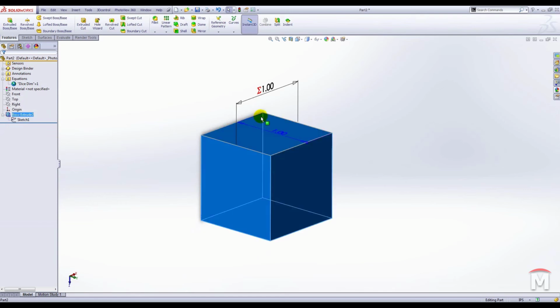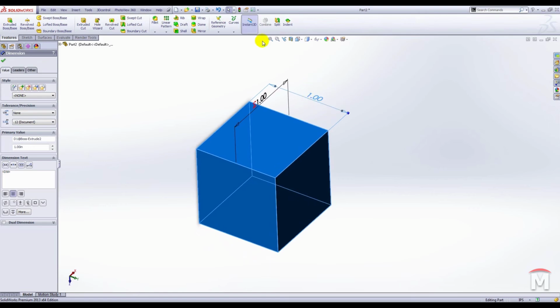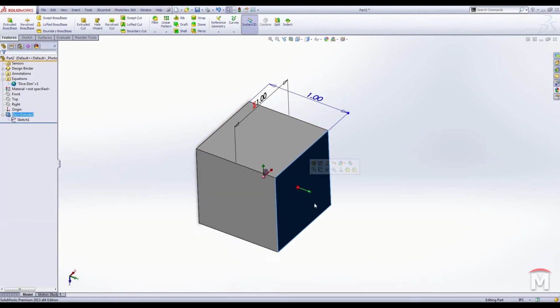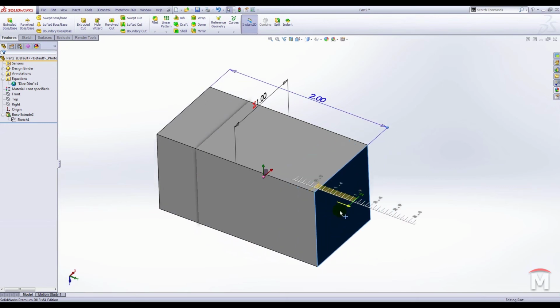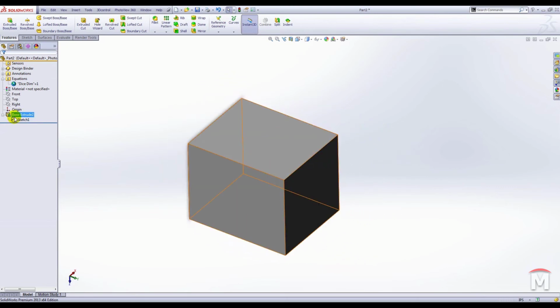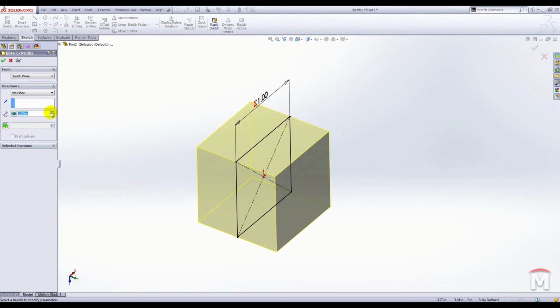One thing you'll notice though, when we click on this guy, there's no icon that is actually linking this guy. So if we grab this face, this thing is still free to be dragged out in space, and that's not what we want. So back inside this feature, instead of putting in the global variable using that drop down, I'm going to type in the equal key, and I'm going to say equals dice dim and hit OK.